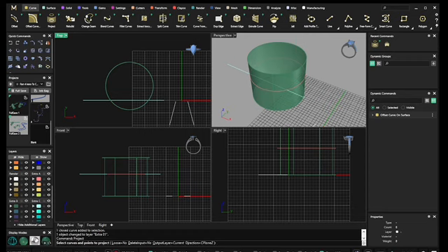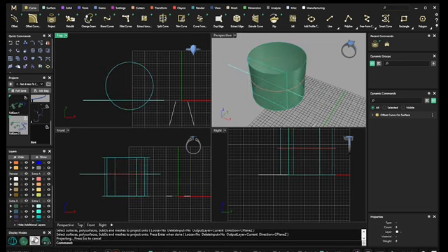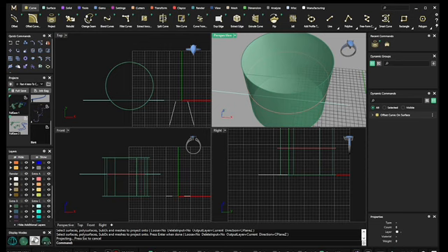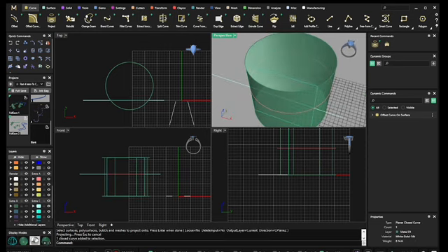I select the word project. I select the curves, press enter, solid, press enter. And because I did it from the top viewport, that is what happens. Now I am going to turn this another color as well.